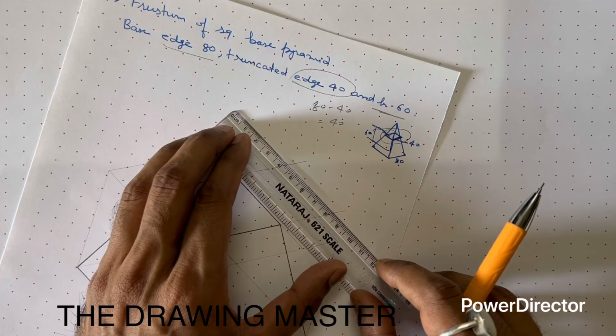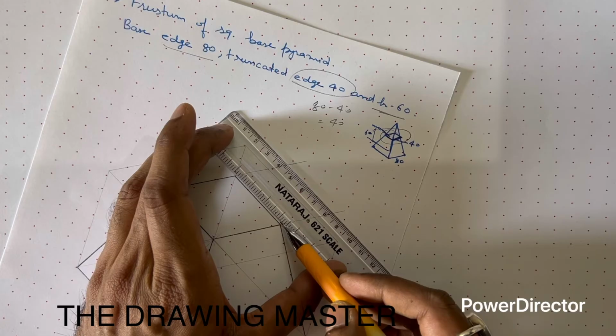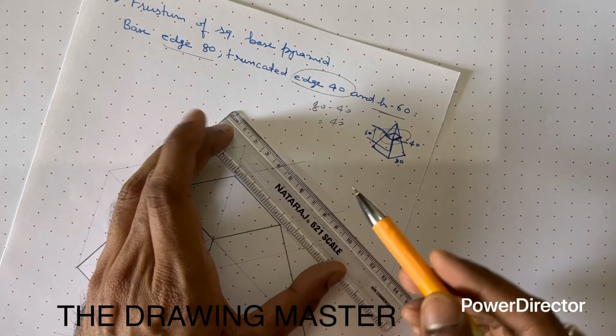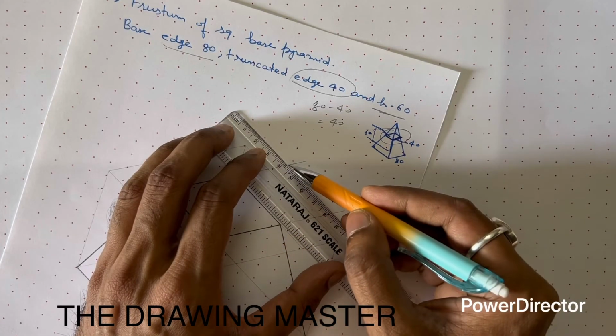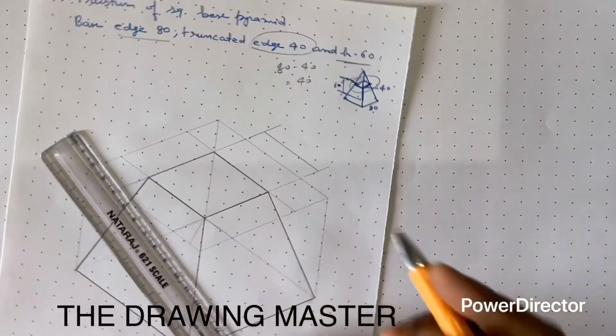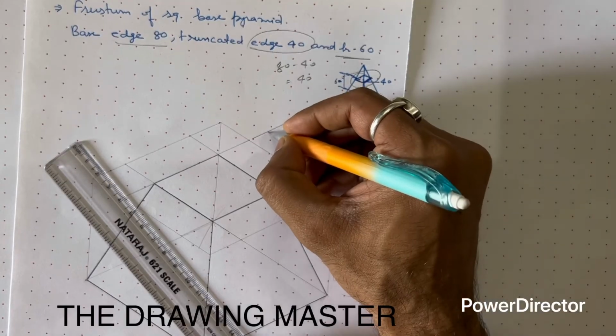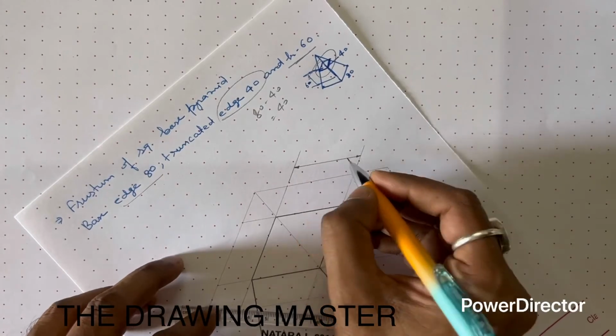Now place your scale parallel to this base edge. Here you can see the scale is parallel to base edge, this truncated edge. So this line will also be at 30-degree. So this is the truncated edge, 40 mm.